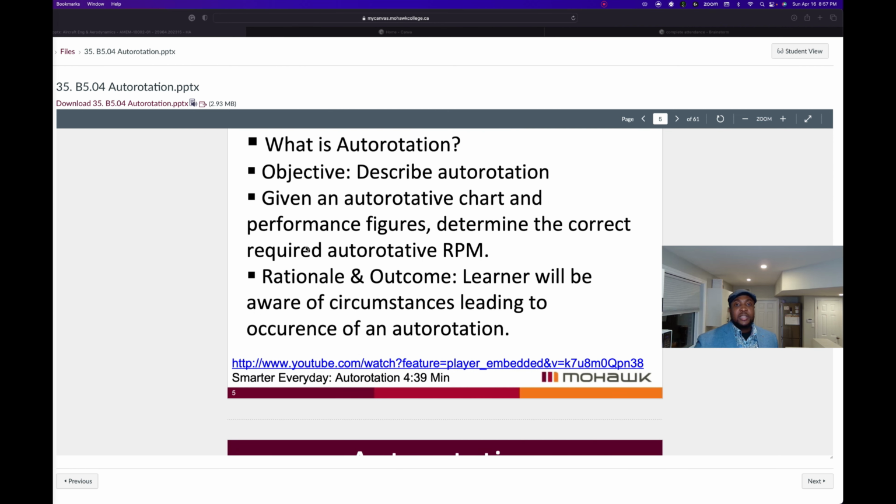Over here, you have sufficient altitude, but you just don't have enough forward airspeed. So you're going to end up sacrificing a good portion of your altitude just to gain some forward airspeed. A hover at 50 feet above the ground is in this area of no operation. Insufficient airspeed and altitude is available to execute a successful auto rotation.